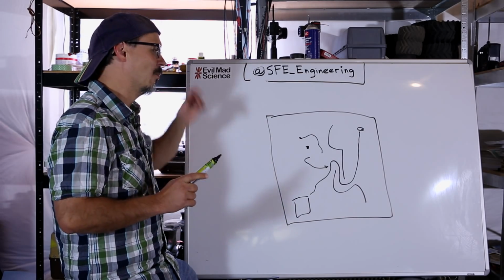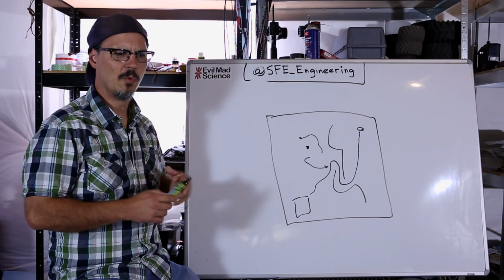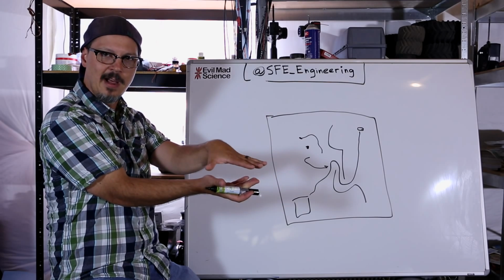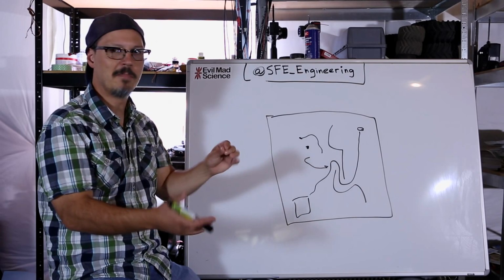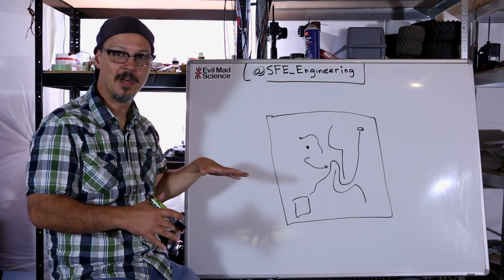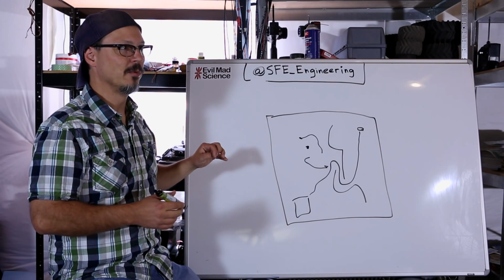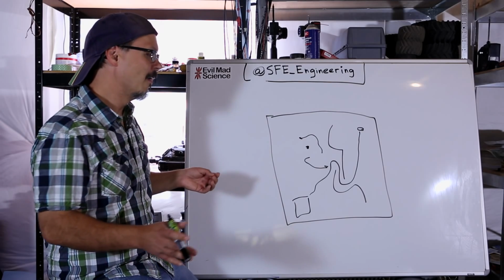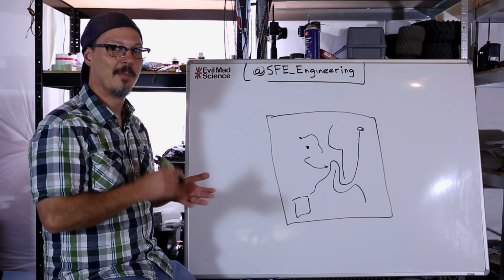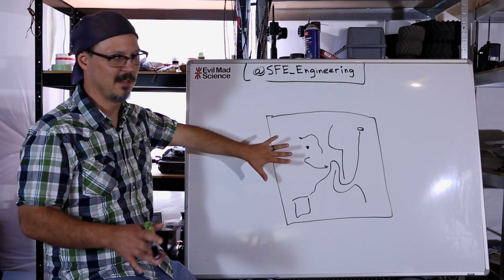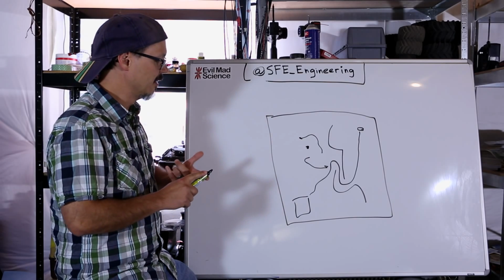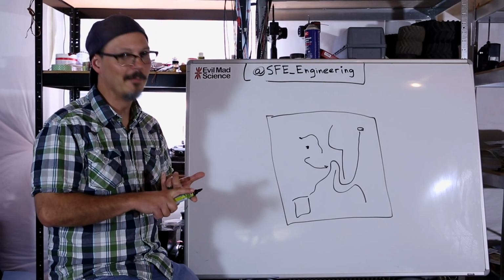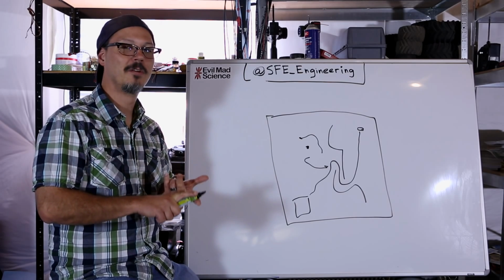Not only that, once upon a time I got bit by a situation where we had a VCC plane on the top, and the solder mask came back a little wonky from the fab house, and there were shorts to VCC everywhere in the circuit, and we couldn't trace it. So ever since then, I'm real shy about putting a top layer VCC plane. Again, don't assume that after you run your DRC, if you've got no air wires, that everything's cool. Watch your ground returns, okay?